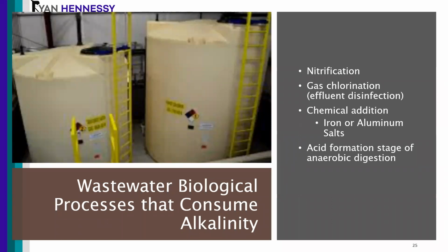So what processes consume alkalinity? Nitrification, we mentioned, has a very big impact on alkalinity consumption. If you chlorinate with gaseous chlorination, which is becoming less and less frequent for disinfection, that's going to consume alkalinity. Chemical addition, like your chemicals that are going to remove phosphorus, your iron and aluminum salts, those will react and consume alkalinity.